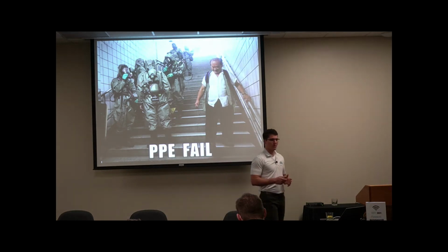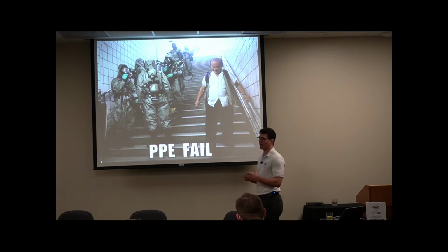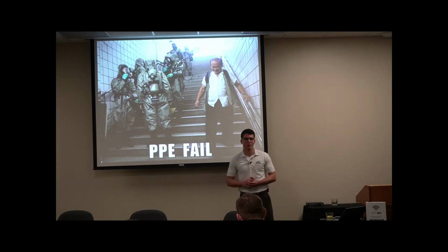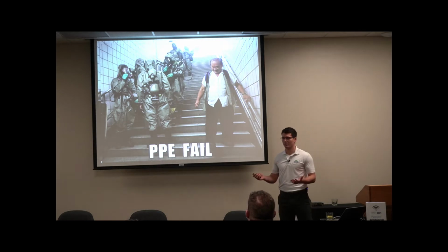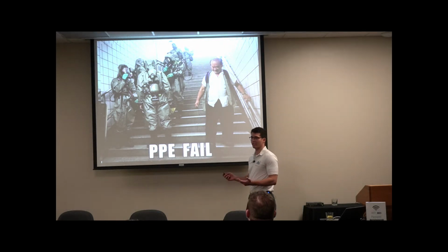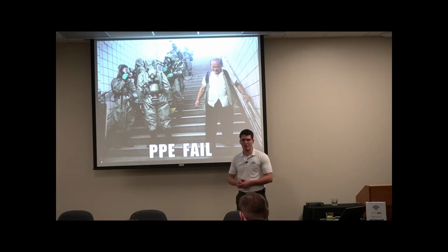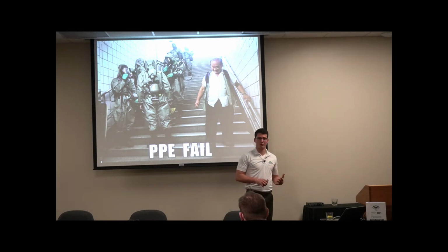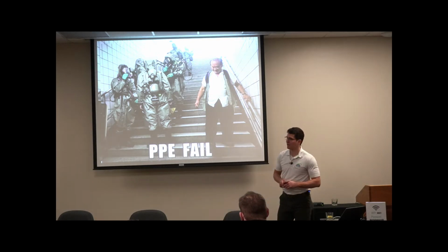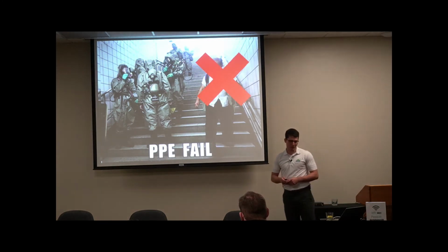But in any case, we want to make sure that we know our exposure, so we know how to protect ourselves. And in the case of PPE, what kind of respiratory protection is necessary to go in that area, all right? Some cases it may be an IDLH environment. Anybody know what that is? Immediately dangerous to life and health environment, which is obviously what this environment is, when I'm assuming they go all the way down to where they need to go. So we're trying to avoid going into places where you're overexposed to certain chemicals unless you have that protection in place. All right, so that's a fail.